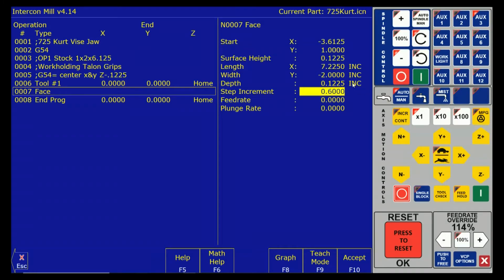You might decide that's too much for my cutter. I need to do it in multiple passes. So that was the question we had. You cannot designate multiple facing passes in this toolpath. I will show you how to do that, but we're going to keep our training wheels on just a little bit longer.